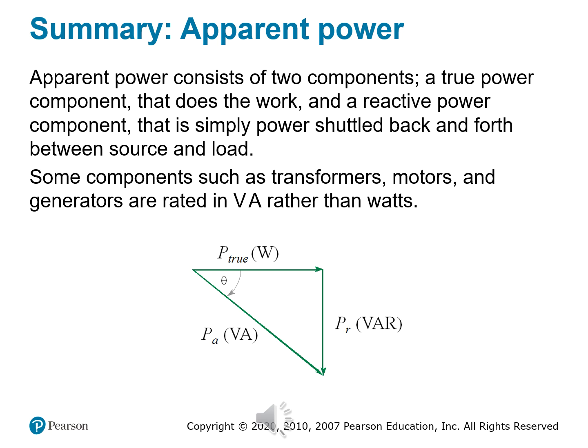And this is important because when engineers size generators or transformers and motors, they don't use watts. They use VA, volt amps. And why would we do this? Because those devices have to handle the total power, both the real and the reactive power. So even if only a portion of it goes into useful work, you have to account for it. That's why transformers list a rating of, let's say, 1 kilovolt amp, VA, instead of 1 kilowatt.